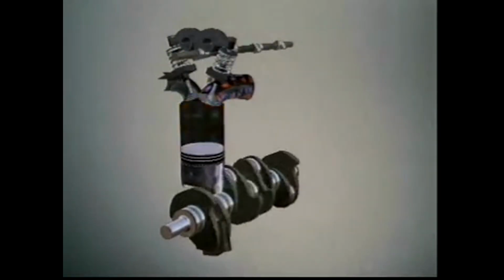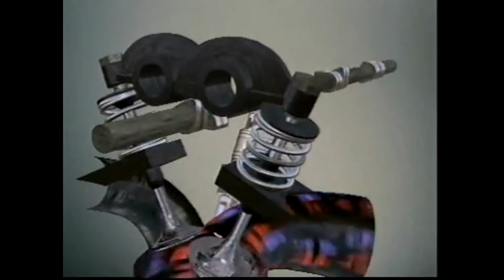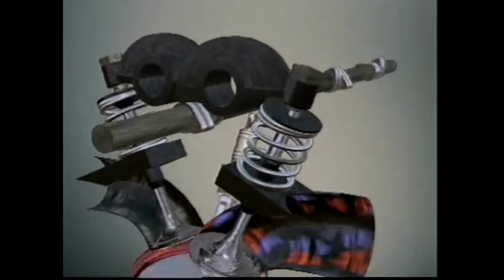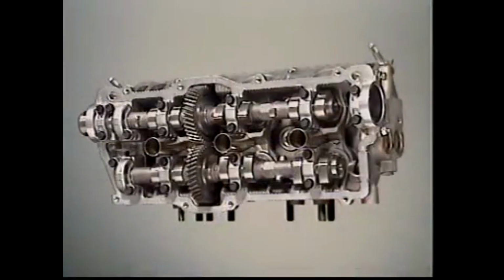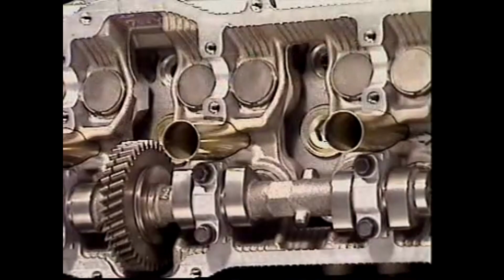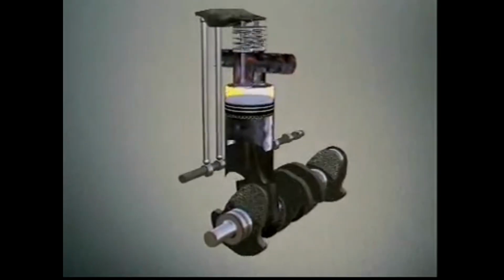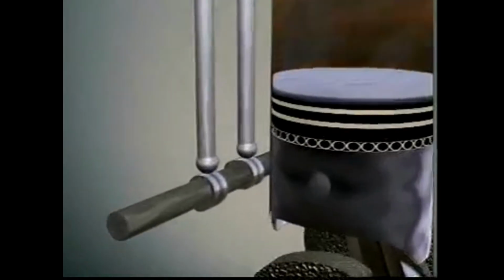The cams control the valve action, but what drives the cams? Cams are attached to a camshaft. In modern vehicles, it's usually mounted over the cylinder head and is called an overhead camshaft. Intake and exhaust lobes can be on the same shaft, or there can be a shaft each for intake and exhaust. Notice that in this design, there's no need for rocker arms. It's a much simpler arrangement.